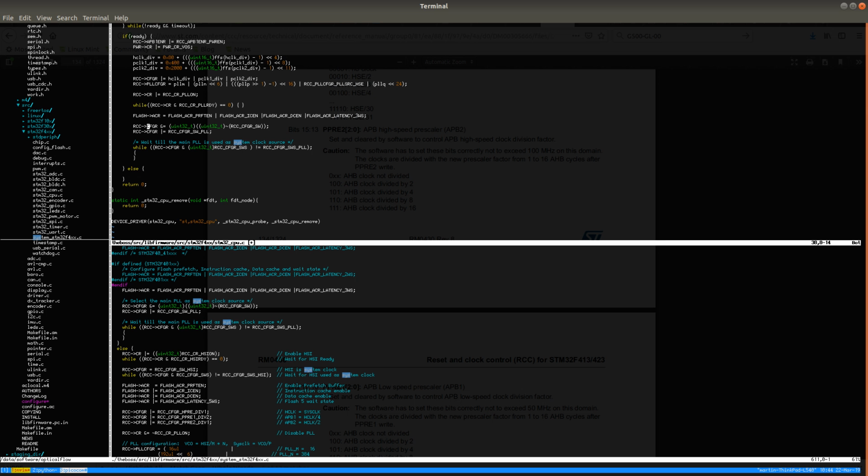This is the source of the main clock, which we now set to originate from the PLL. And oh, this was really just totally useless code from the library, where they had a semicolon after the while loop, and then they had the section below it, which would never run, or actually which would always run if there was any code in there. And then this waits until the PLL is actually selected for the main clock.